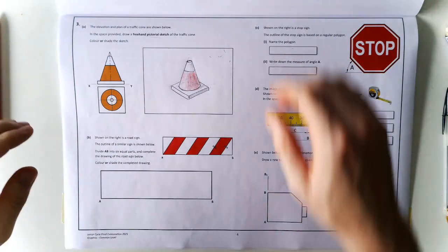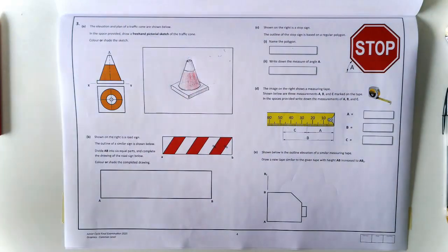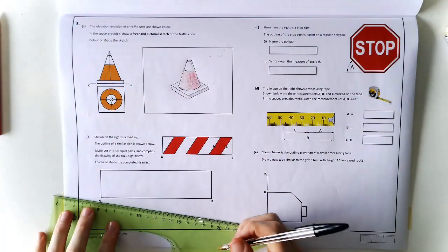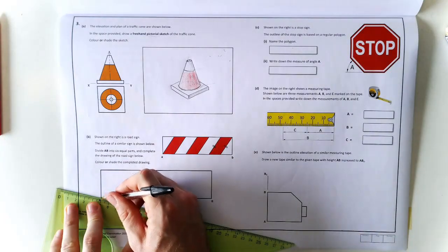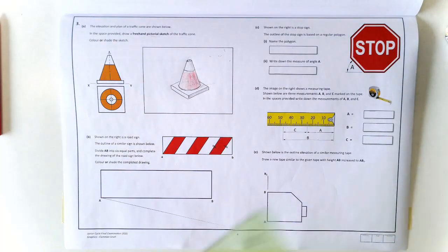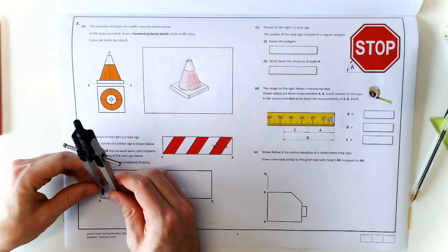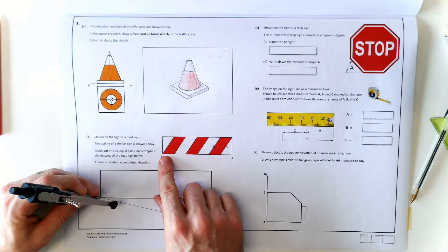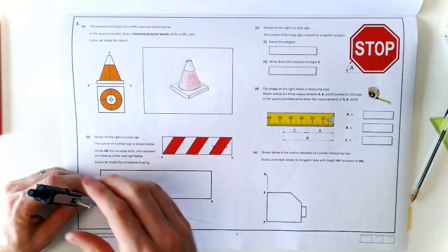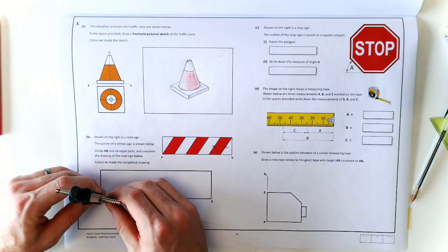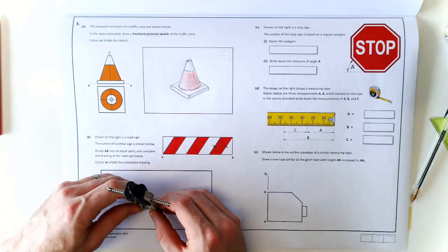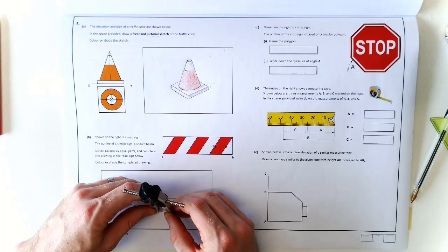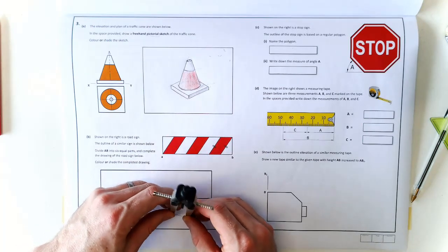It's a pretty simple construction. So we want to go a line from A or B, it doesn't matter, and it's going to be at any angle. So there's my line at any angle. I'm now going to get my compass. I can set it to any distance. From A, I'm going to step off 1, 2, 3, 4, 5, 6. So any distance there on my compass. 1, 2, 3, 4, 5, 6 for my 6 equal parts.